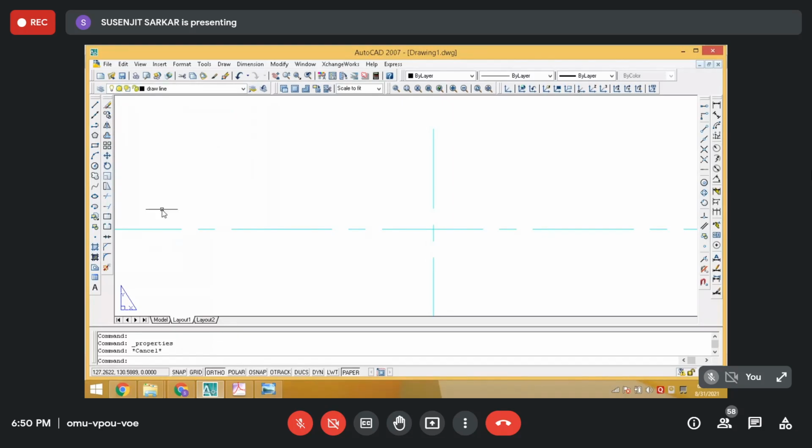I select that particular layer, then go to the circle command. Then object snap on. Track on. Intersection point. You get the intersection point, right?